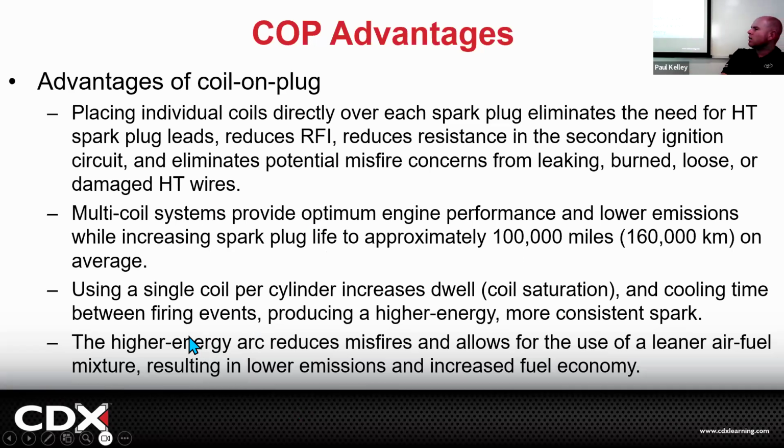And also because of the higher energy arc, the increased dwell time reaching its full potential, and using different windings and less resistance, it will allow us to run a more lean air fuel mixture. That's a big deal because if we can run more lean, that means we can have better fuel economy and potentially lower emissions, as long as we deal with that oxides of nitrogen.